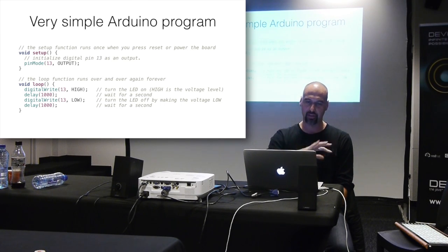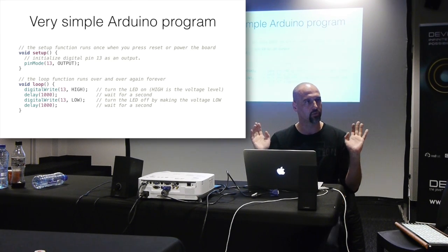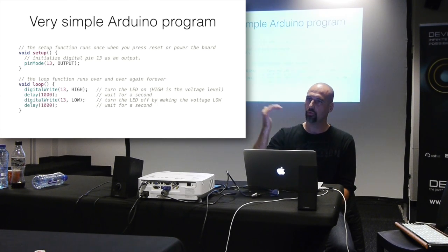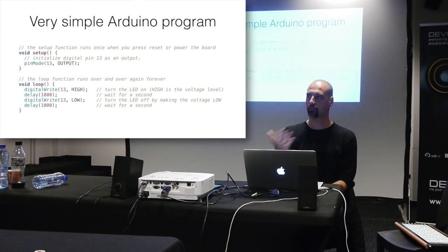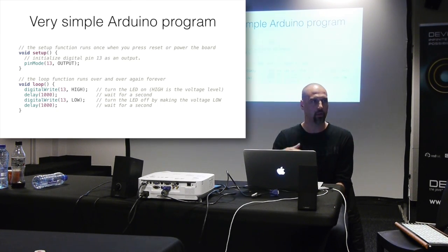So this is a very basic, completely functional Arduino program. You've got two methods that summarize everything that you do. That's actually the only thing that's happening. You've got a setup method that is loaded when your board starts up or when it reboots, and then a loop method that is constantly being looped over forever and ever at 100% of CPU power. So that, to me, as a Java programmer using general purpose CPUs, was really weird to think of, that it's actually always going full speed ahead, and it's your responsibility to keep everything going as quickly as possible in your code.